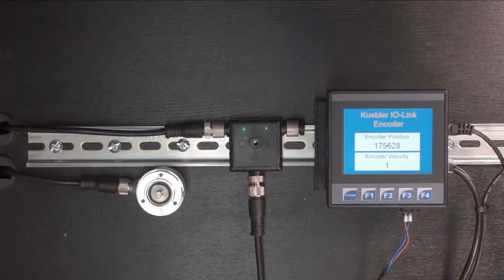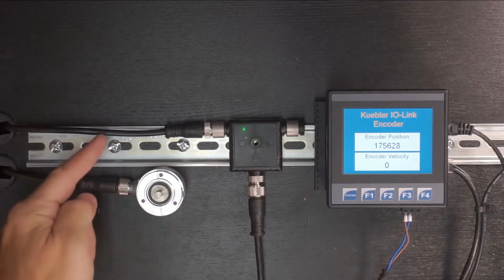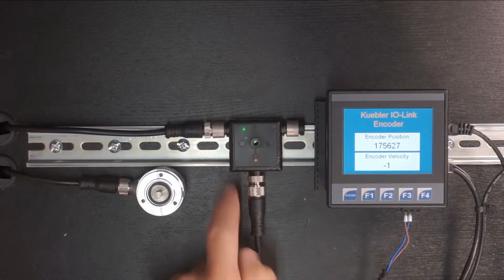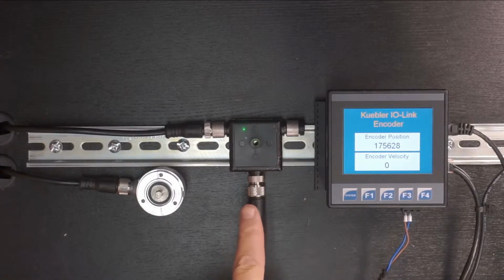All right, so now we'll take a look at our bench at runtime. We're no longer configuring the system. Now we're actually at runtime. So what we have now, we still, of course, have the encoder connected to the IO-Link master, but now the IO-Link master, instead of being connected to the configuration tool, it's connected to the runtime Y cable for connecting to the OCS. So this is the base of the Y, that's the M12 connection.